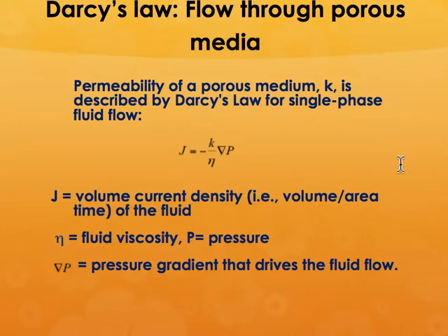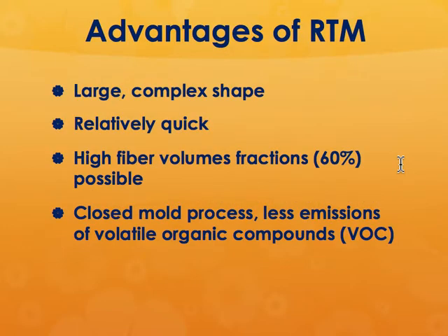You know the viscosity, you know the pressure that you need to apply for infusing it completely, and you also understand the pressure gradient that will drive this fluid flow and fill this entire preform. So that's the law that is going to govern processes like resin transfer molding.